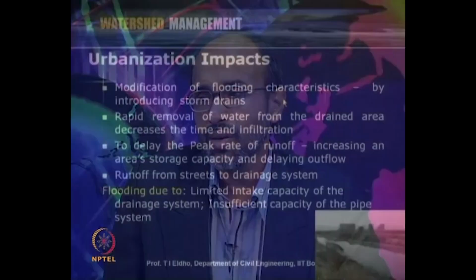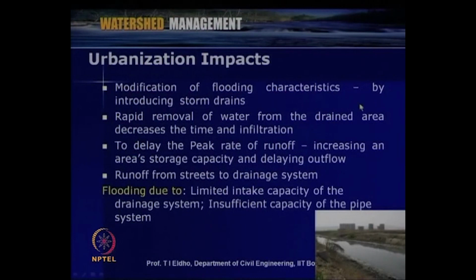So, the major issues of urban flooding are loss of life, economic loss, and disturbance to the transportation and telecommunication systems. Also, the urbanization impacts modify flooding characteristics by introducing storm drains in many urban areas. Rapid removal of water from the drained area takes place, as we discussed, since the time and infiltration decrease, increasing the peak rate of runoff.